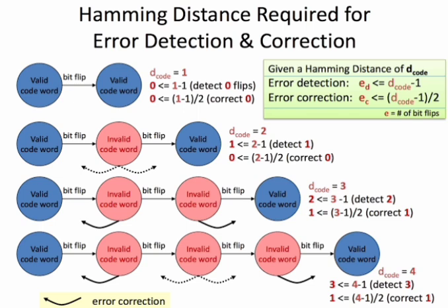The significance of the above bound is that an (n, k) linear block code is able to correct up to t errors when the total number of syndromes is not less than the total number of all possible error patterns with errors up to t locations, including the no error condition.